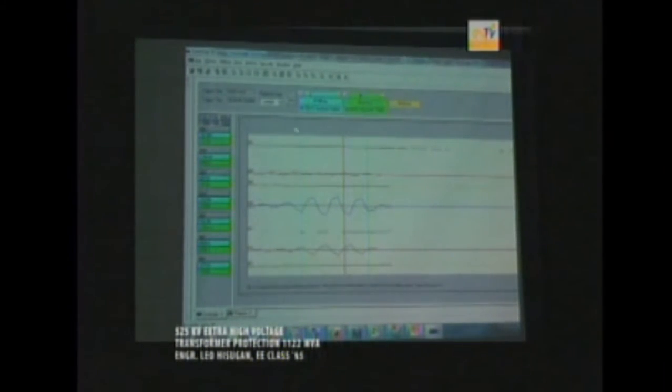You can see here, if this is your phase Bravo, phase Charlie here, and your phase A over here, what happened to the shunt reactor bank on the delta tertiary? What kind of fault was present there? Is it an A phase fault, a B phase fault, or a C phase fault? Based on the waveform here.